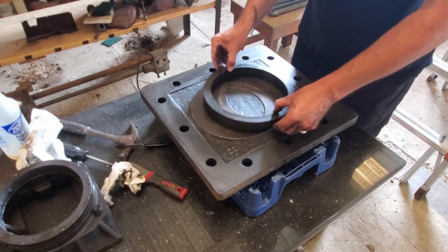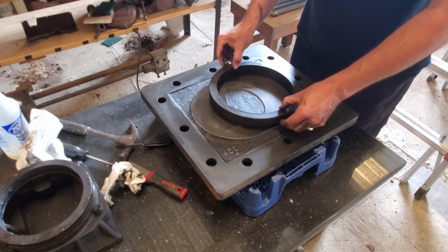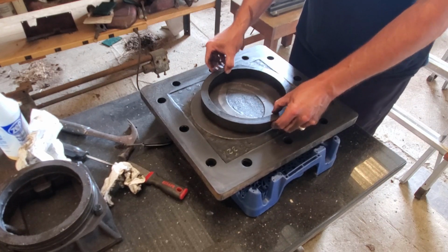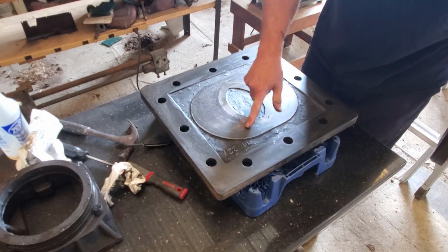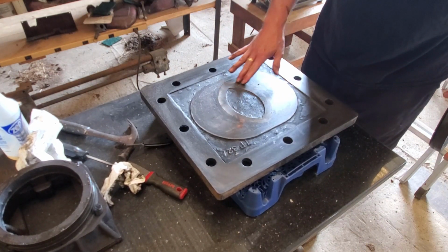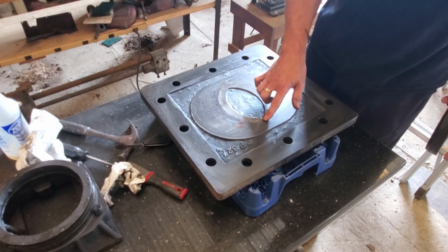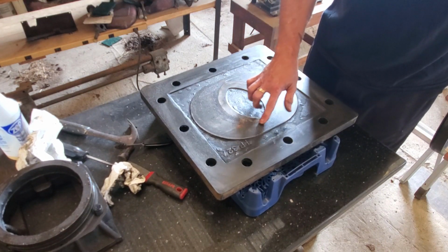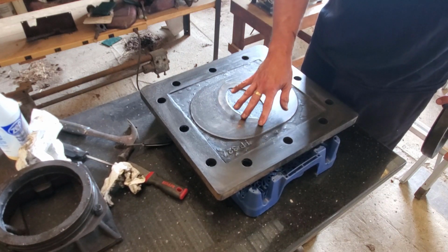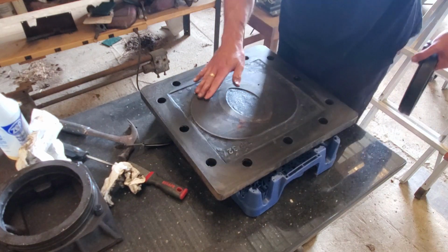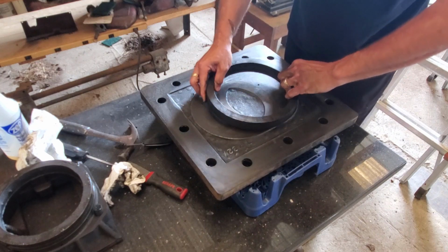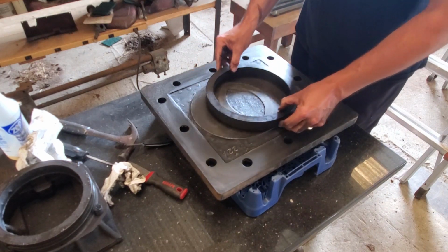Back side of that balance piston will be going back and forth, and then as the machine governs itself, that travel is going to become less and less. Some kind of a copper repair in here. This area, the unworn area, you can definitely feel it's raised compared to this. I would say several thousandths, at least maybe 5. But Dave's gonna machine this all down and give me a nice flat surface within 1/1000ths.